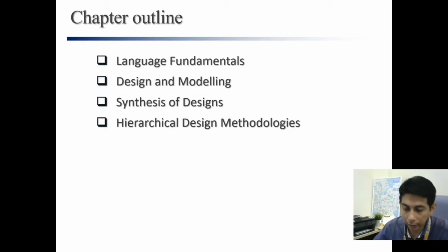All right. Sometimes you need the data flow modeling. Sometimes you need the behavioral modeling, and sometimes you need the structural modeling. Depend on what kind of circuit that you design, and also depend on your experience. Yeah, and also depend on the constraint that you have. For example, if the design is quite complicated, quite big, you cannot go for data flow modeling or structural modeling, so you need to design using behavioral.